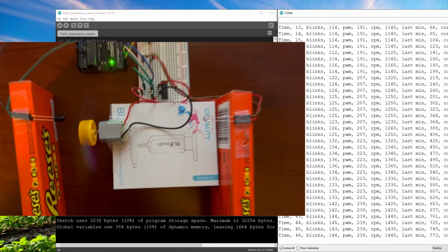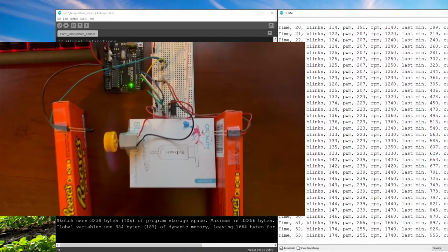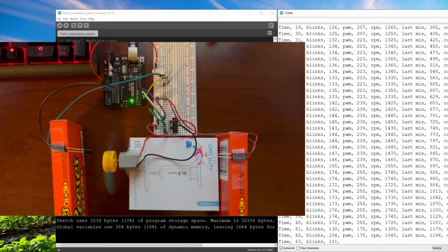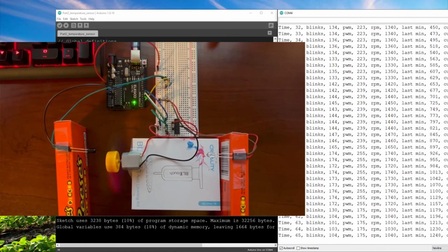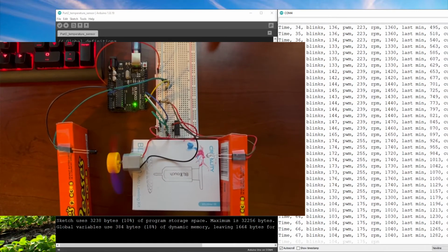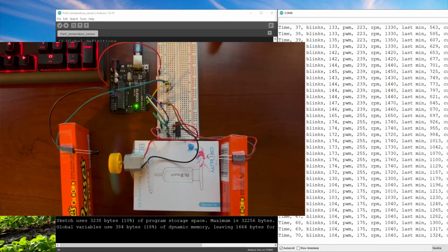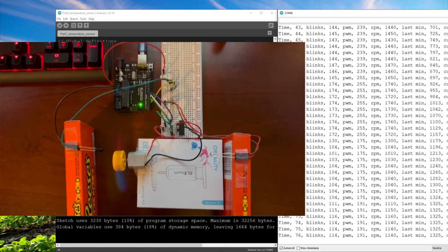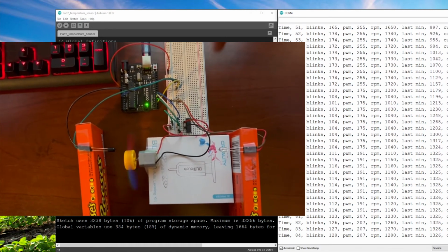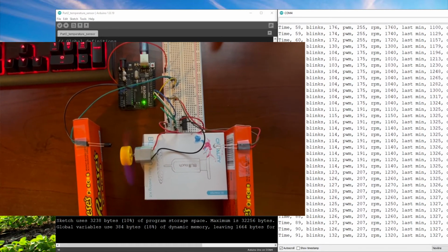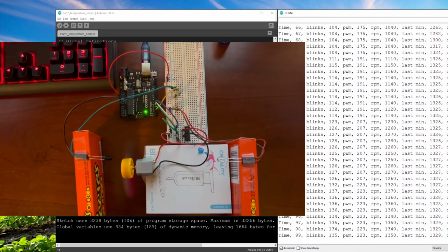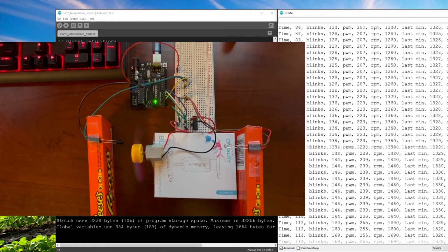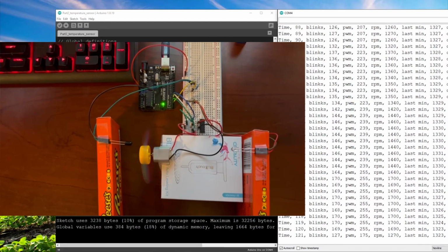as we hit that. The fun aspect of this demonstration is that the PWM is in a loop. There are 6 different states from that 175 to 255, and each one is a 10-second period. So we actually average out to a pretty constant RPM over the past 60 seconds once we get around to the 70-second mark after it's spun up and backfilled the zeros in the blink array. And I let it run through 2 full iterations, 2 minutes of these pulse width modulation shifts, until turning it off, and we can see that the blink counter goes down to 0 along with the RPM.